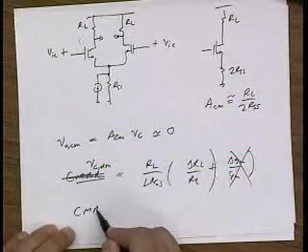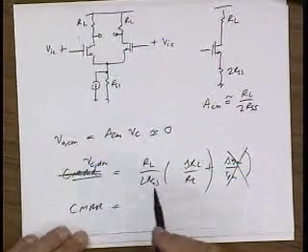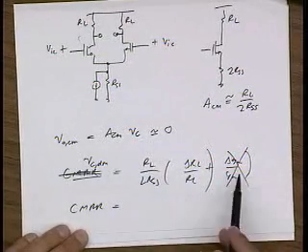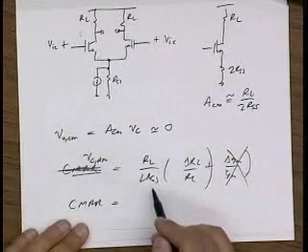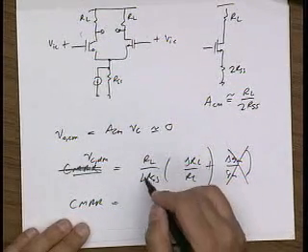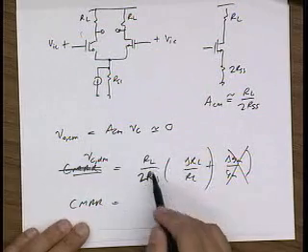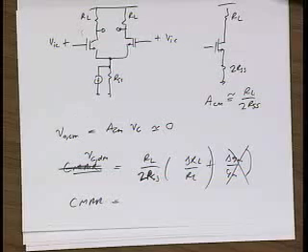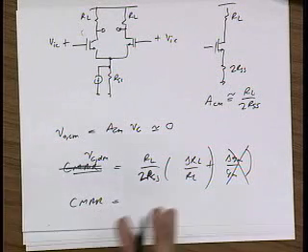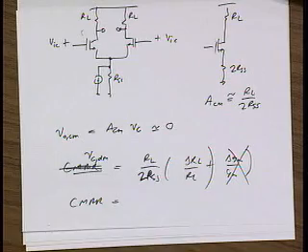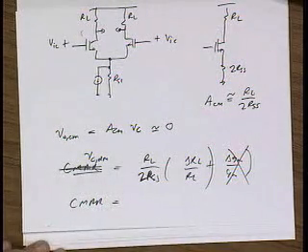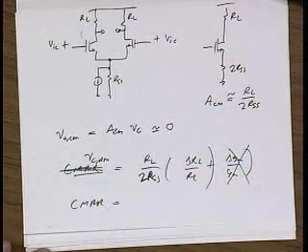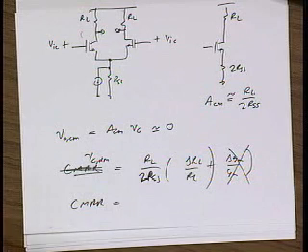So if I look at the common mode rejection ratio, I have to divide this by the differential gain, which is just GM RL, right? And so then you see how I end up getting, so this is 2 RSS. So then this RL cancels out, and you end up getting a factor of 1 over RO, the output impedance again. So you actually get a big improvement, 1 over GM RO kind of improvement. So if you can get a gain of 20, 30, that directly improves your common mode rejection ratio. Okay, that makes sense to everybody?